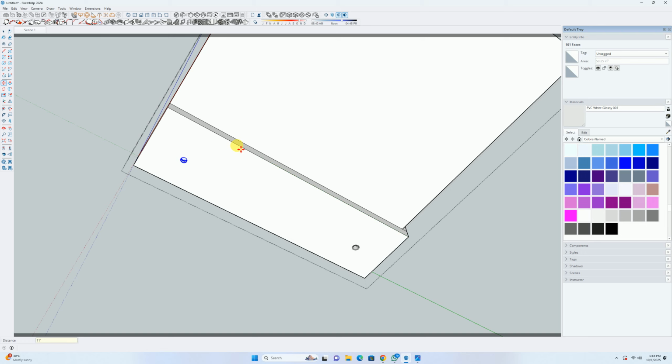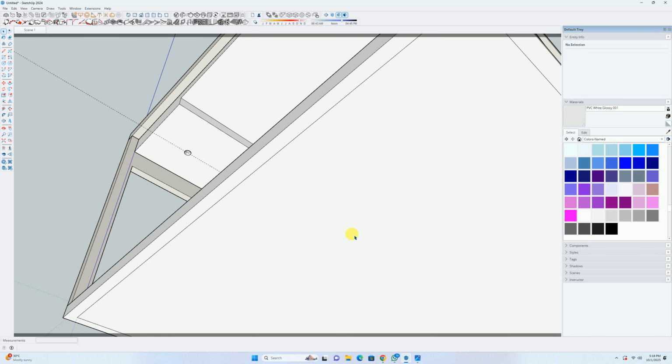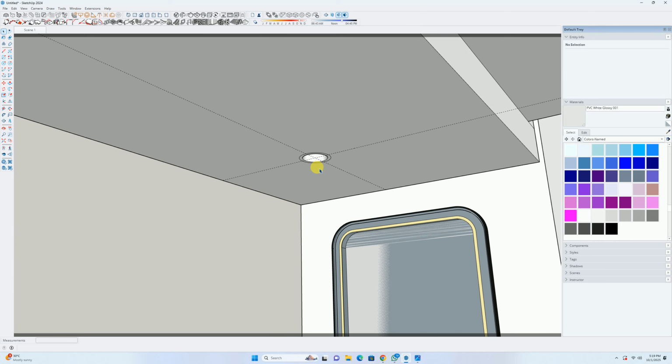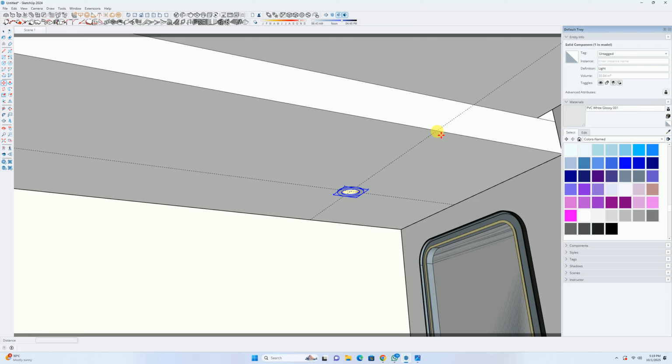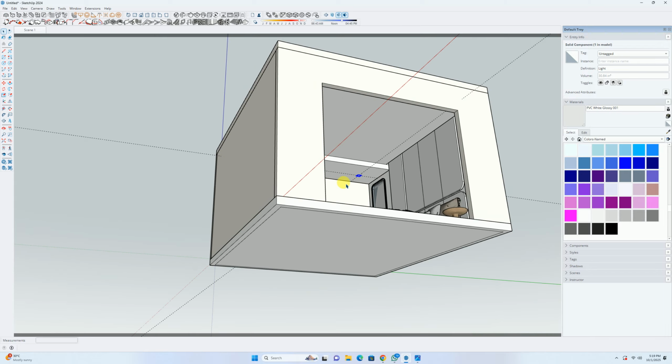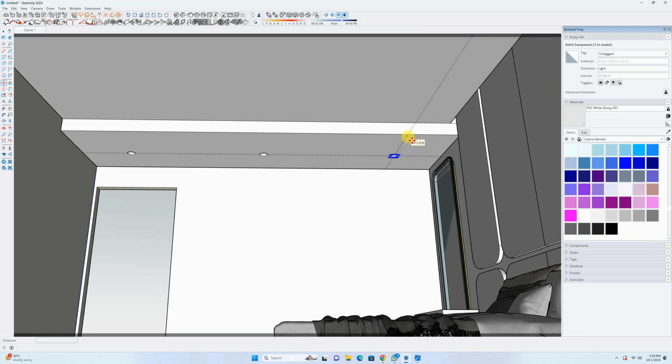11 feet, and then I'll apply a divide feature and divide it with three segments, or I guess three segments are quite large, so I'll divide it by two segments. So in this manner we have created three holes for light. Now I'll select this light. I'll copy this light from this line, green axis, for 11 feet.